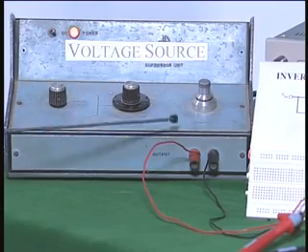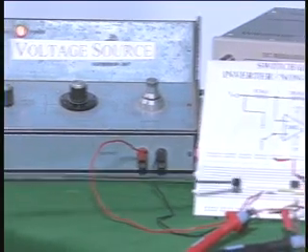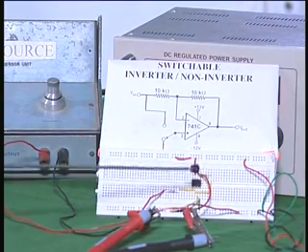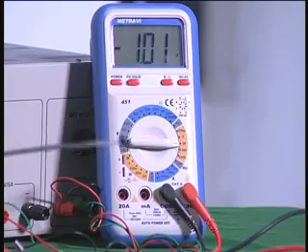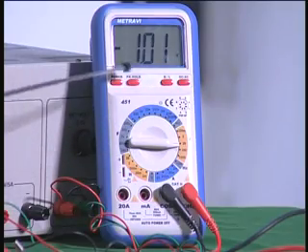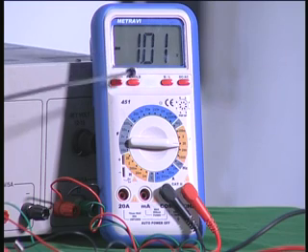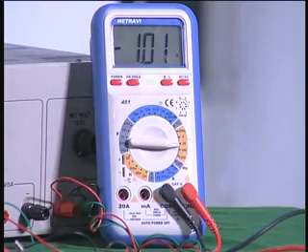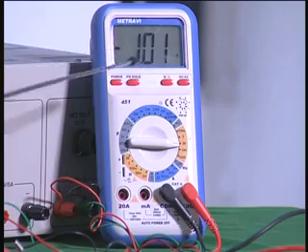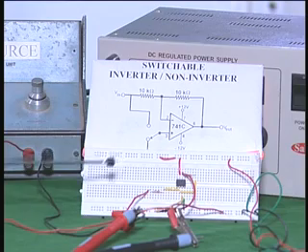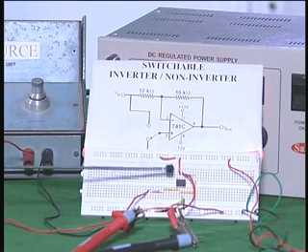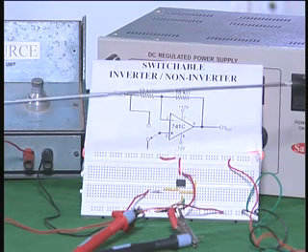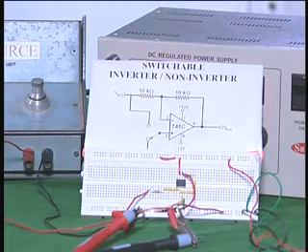This is a millivolt source, and the output of the millivolt source is connected as the input, and the output of the operational amplifier is connected to a multimeter which is in the voltage scale, and it is now reading minus 1.01, which is the output voltage. So the output voltage now for this circuit is minus 1.01. Now what I want you to see is, let me quickly take out the multimeter from the output and connect it to the input, and at that time you observe what the multimeter reading is.